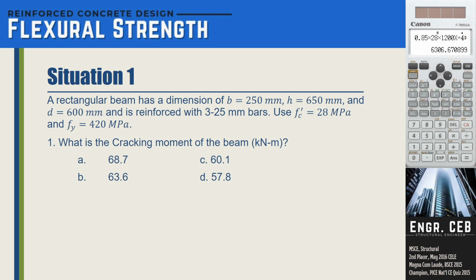We analyze a reinforced concrete beam using two ways. First is the elastic method, meaning we will consider the composition of concrete and steel as an elastic material, so we will use the principles in strength of materials in analyzing it. The other way is the ultimate strength design, meaning we will base the analysis of the reinforced concrete on limit states of the concrete and steel.